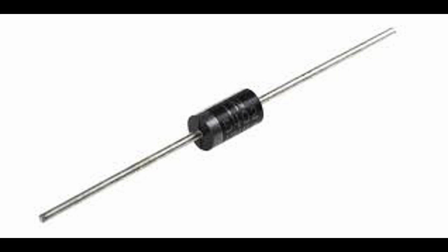Zener diode characteristics. Zener diodes are designed to operate in the reverse biased mode, meaning the voltage across the diode is applied in the opposite direction of its normal forward biased operation. Under reverse bias, Zener diodes exhibit a very sharp breakdown voltage characteristic. When the reverse voltage across the diode reaches its specified Zener voltage, Vz, it starts conducting and maintains a relatively constant voltage drop, Vz, across its terminals.